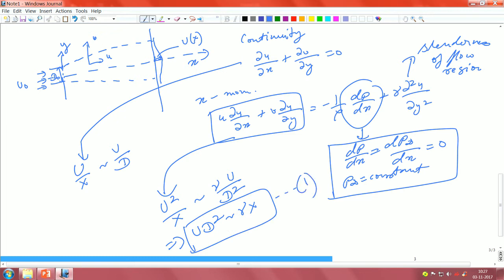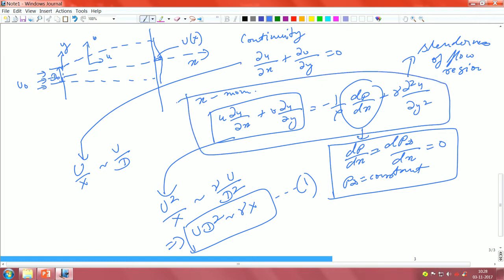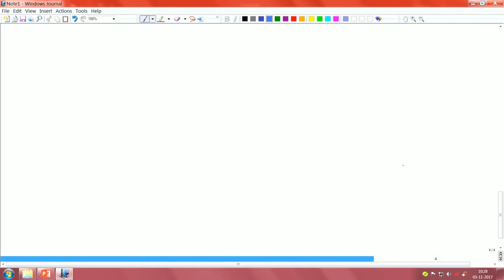This is nothing uncommon, this is what we got in our traditional flat plate boundary layer equation also. This is a very similar looking equation, there is nothing very drastically different about it. We have still applied the same slenderness or the boundary layer type of concept over here. And of course, we have taken dp infinity by dx to be equal to 0, because we already said that it is flushing into a reservoir where the pressure is constant.